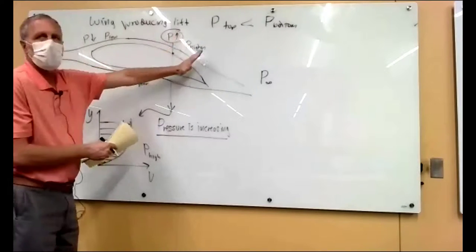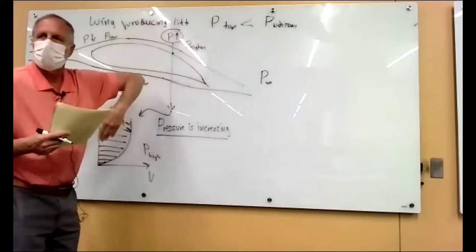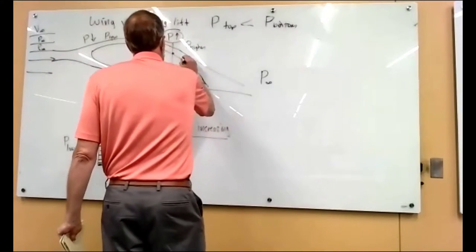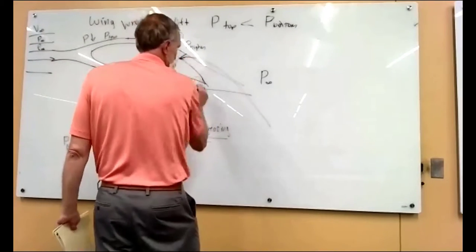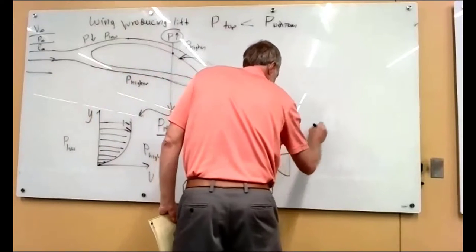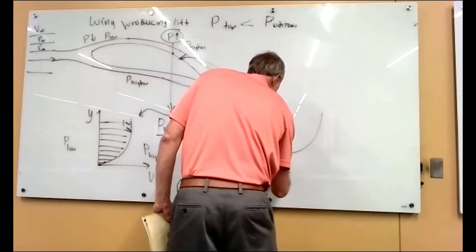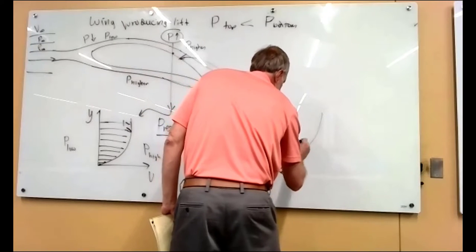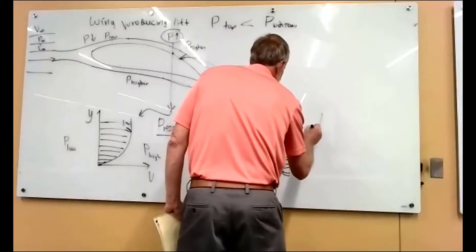The pressure is always higher as it's going into it, so it's slowing and slowing and slowing the flow. So when you get down maybe to a point here, your boundary layer looks like this. Some of the really low velocity air near the surface has actually been pushed backward to the point where it's going backward.